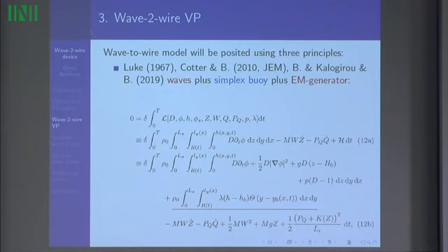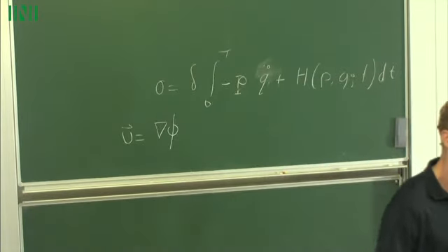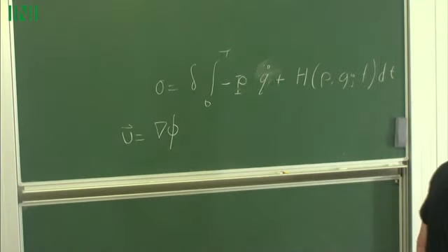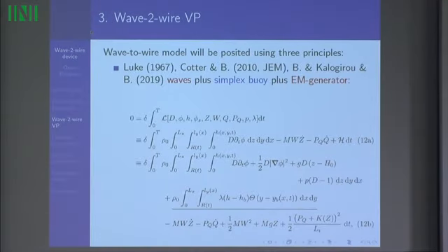So then here, the m w is like the P, the Q is the position, and then you see here half m w squared is the kinetic energy of the buoy motion, and m g z is simply the potential energy of the buoy. And this is the kinetic energy of the circuit, and this is the kinetic energy of the water, so it's in the field under the integral, and this is the potential energy of the water. And then this glues, this is an important term, this glues the water and the buoy together.